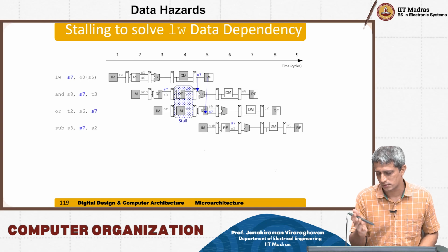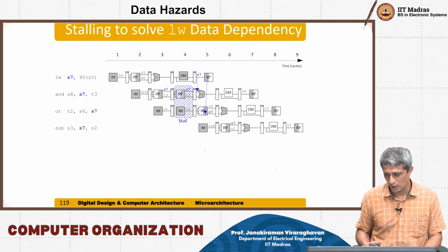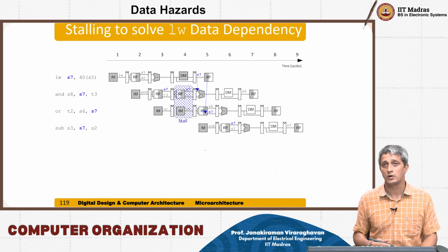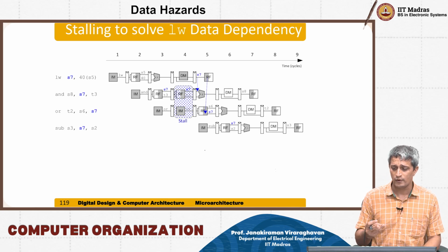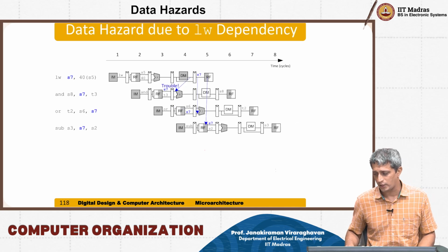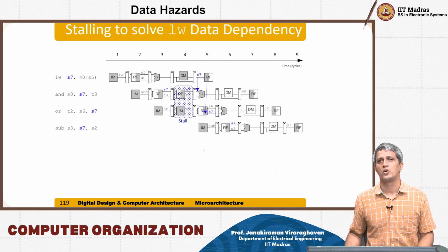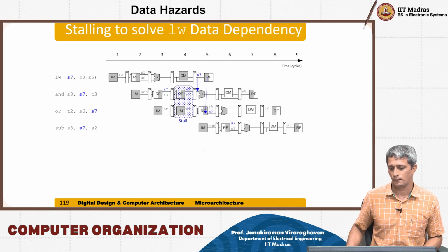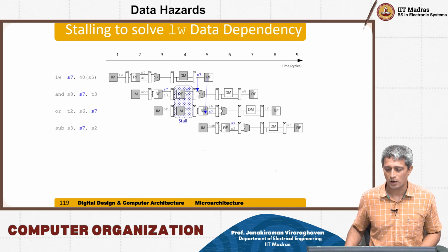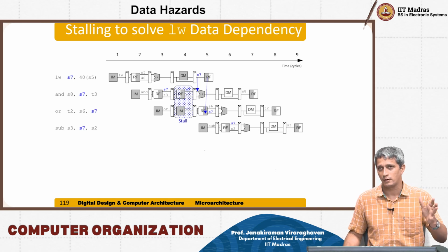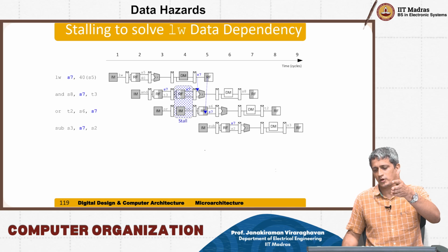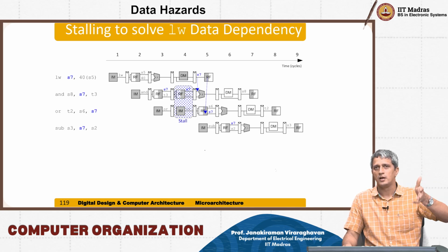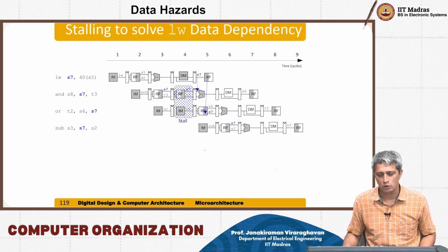So that is how this stall operation is going to work, which means that earlier, the operation that took 5, 6, so if you look at the previous cycle, in 8 cycles we finished. Now you have no option but to go to the extra 9th cycle, where 1 is a stalled cycle. So basically this is what you want to stall. Now you have to stall everything. When you say stall, remember, in one you will be doing a register file read, in another you will be doing the instruction memory fetch, all of that you have to stall.